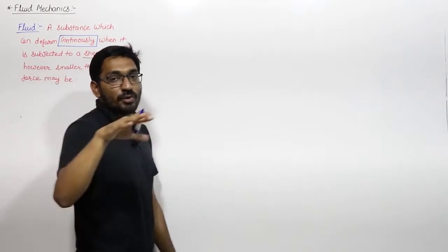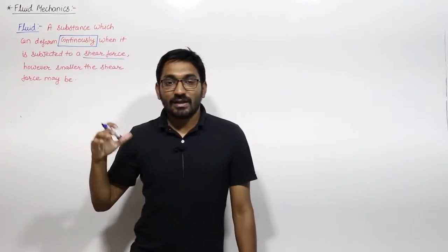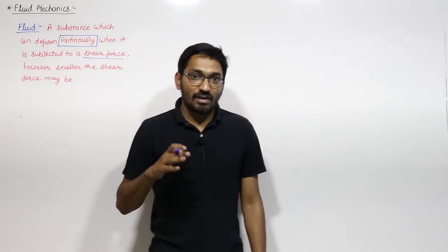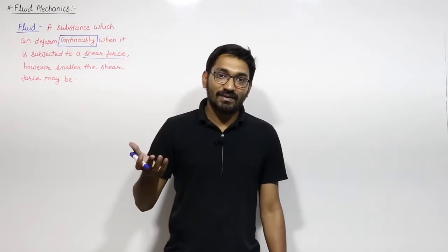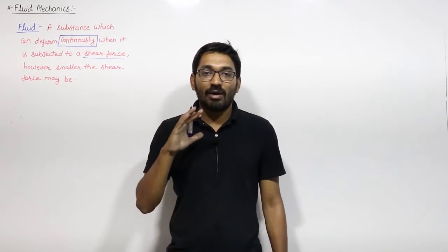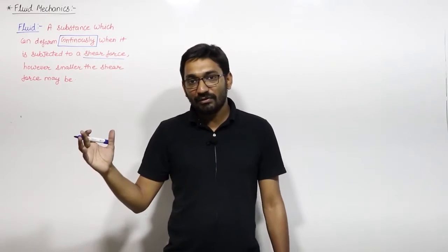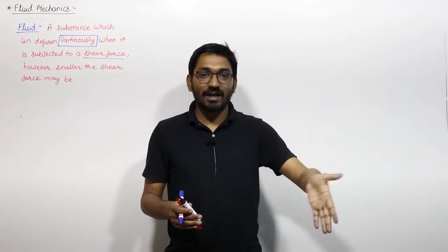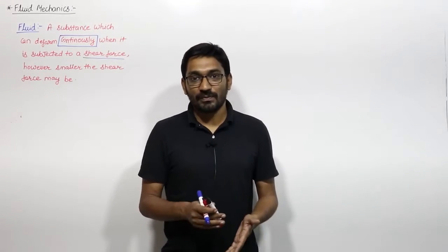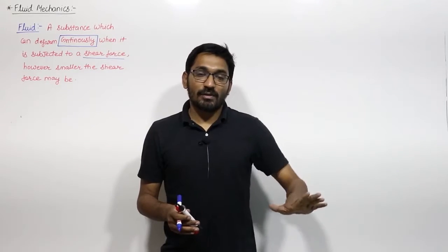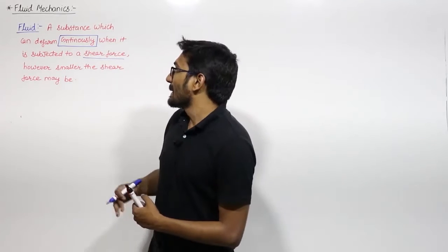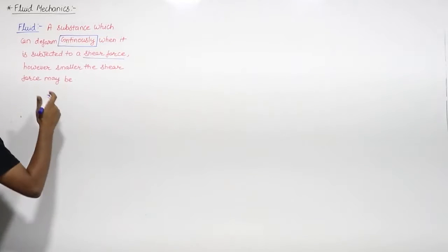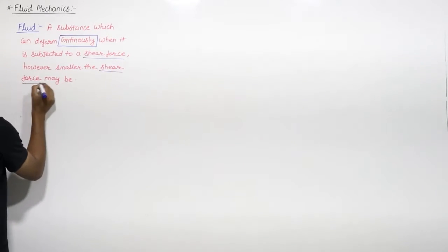This is important. Fluid will deform continuously when it is subjected to a shear force. If you apply a shear force on a fluid particle or a fluid, then it can deform continuously as long as that shear force is acting. If that shear force is acting for, let us say, 10 seconds, then it is continuously deformed for 10 seconds, and when you remove the shear force or the shear stress, the fluid flow will stop at that point only where you remove the shear force. And fluid will deform even if the shear force is very small.